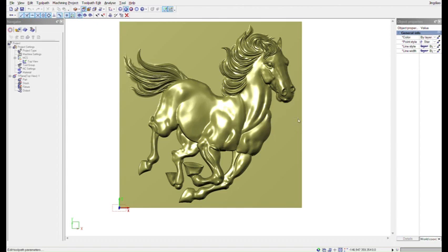In the avoid settings I am going to make the start point, because if you do not give this start point in your design, no problem, but it will automatically select the start point, and then you can't control it. So in that case I am going to select the 0 0 coordinate and a little bit, 1 millimeter, away from the block. So I will select that starting point for safety conditions. And that is okay, and everything in the basic settings.